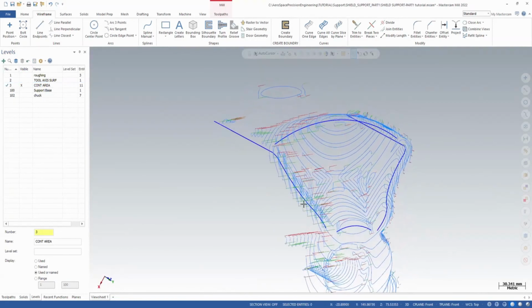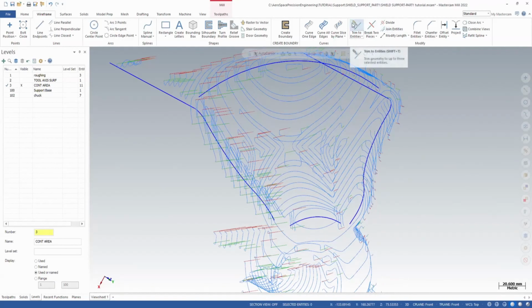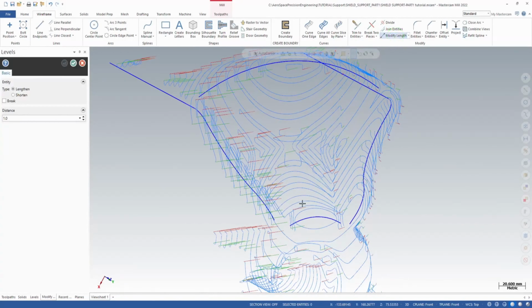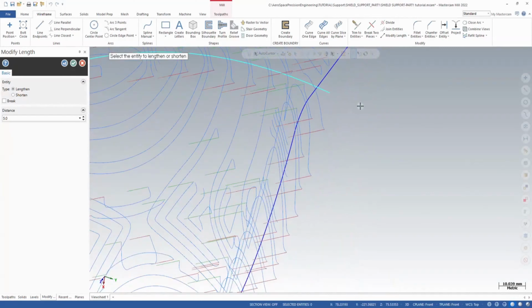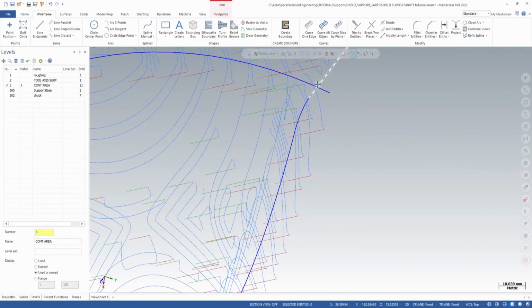Everything together, the pocket near all the wireframe will be set, and you can see the result. If the containment is not set, the toolpath will be generated based on the previous stock model. So you must set the containment boundary.